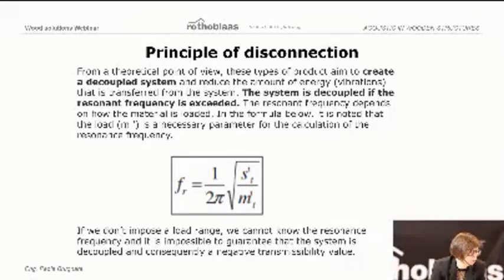So first of all, we need to know the elastic properties of the material, which is defined with S, and then we need to know the load applied on the material, which is defined with M. So it is clear that it is not possible to estimate the resonance frequencies if we don't know the load applied on the profile. And if we cannot calculate the resonance frequencies, we cannot define if the system is decoupled or not. For this reason, there is no acoustic profile that can work without knowing the load applied on it.